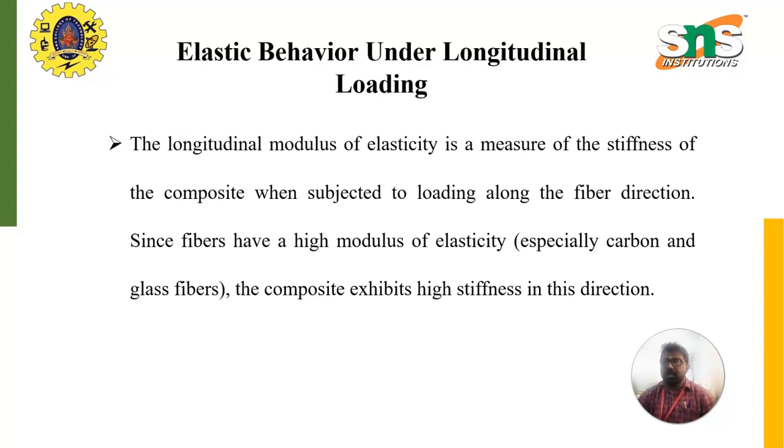The longitudinal modulus of elasticity measures the stiffness of the composite when subjected to loading along the fiber direction. The fibers are aligned with the direction of the applied force, so the matrix plays a less significant role in resisting the longitudinal loads compared to the fiber.